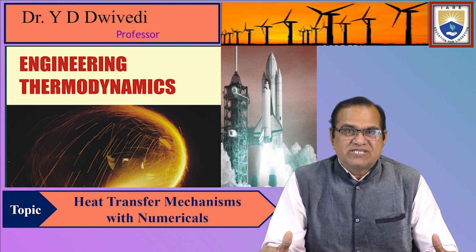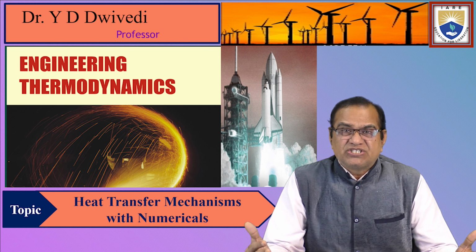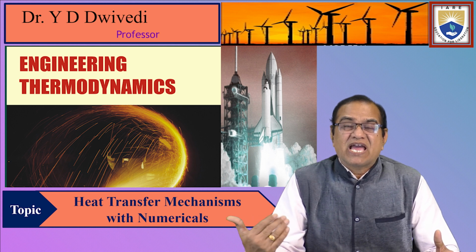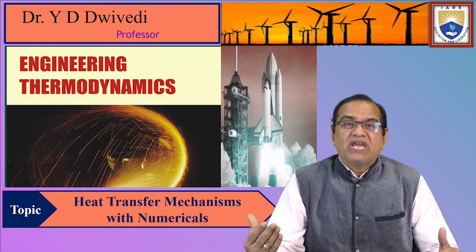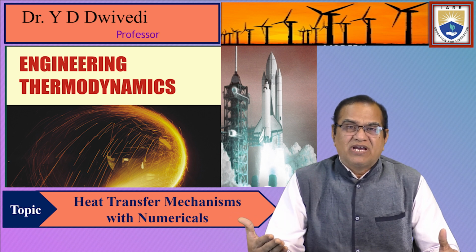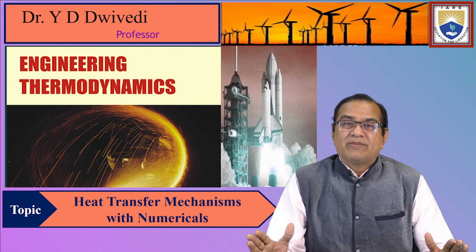In respect of this, Carnot has devised a cycle in which, for a given temperature range of high and low temperatures, the maximum efficiency can be produced by the Carnot cycle. In the Carnot cycle, we have 2 reversible adiabatic or isentropic processes, and 2 isothermal processes. And by that, we can get the maximum efficiency.